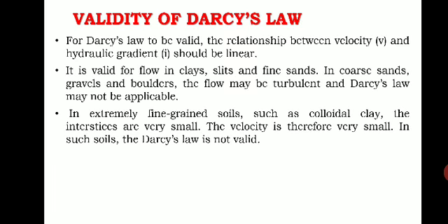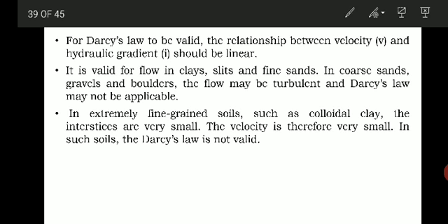Next, in extremely fine grained soil, such as colloidal clay, the interstices, that is the gaps or the voids present in between the particles, are very small, and the velocity is therefore very small, and for such soils Darcy's law may not be valid.